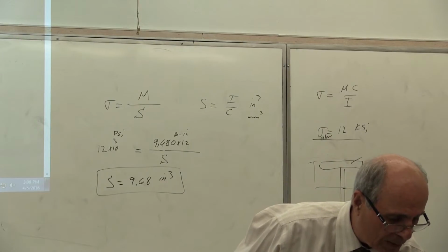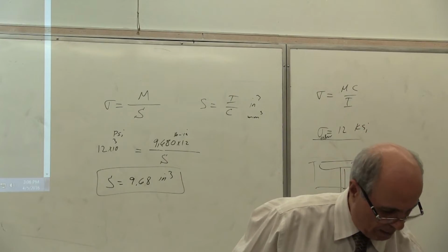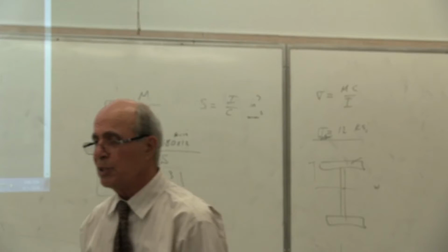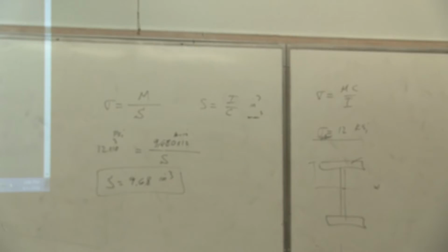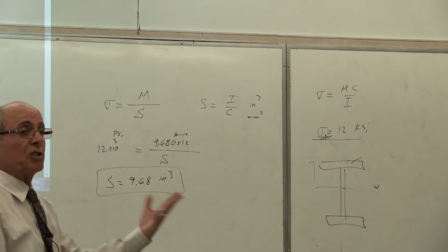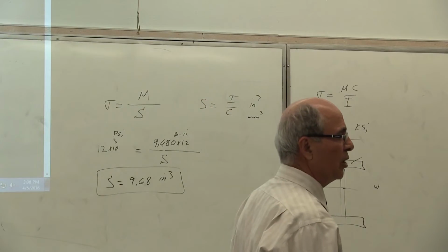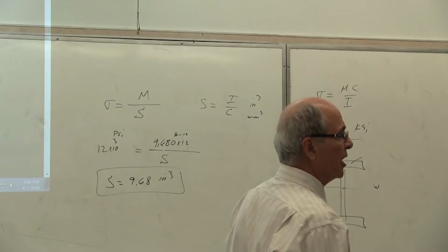You see the minimum is how much? 5 point something. Everybody see that at the bottom of page 19? Is that a good section? Of course it's not. So you go up. Which one is qualified? 8 is not good, but 10 is good. Yes or no? 10 is larger than that because this is the minimum required. Anything larger than that is stronger. Anything less than that is a weaker section. Yes or no? Because S is representing the I. Is that correct or not? Yes? Are you following there? Are you having the table there? Yeah, share it. Okay.